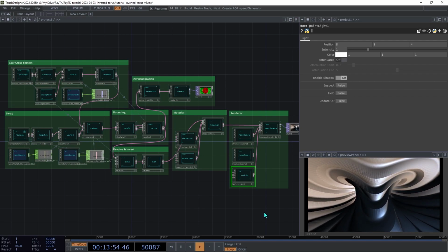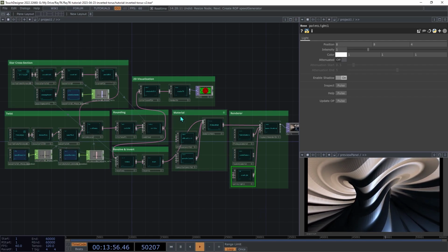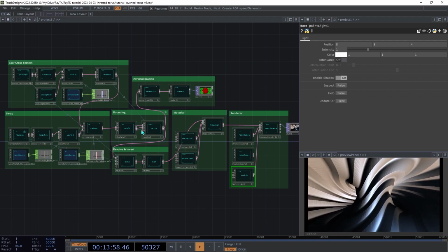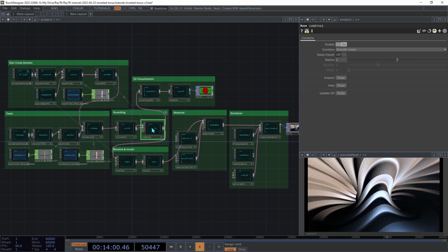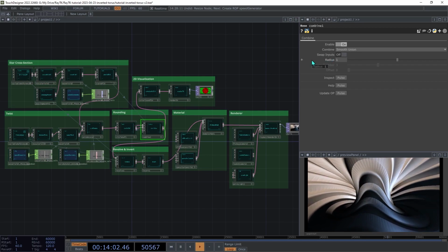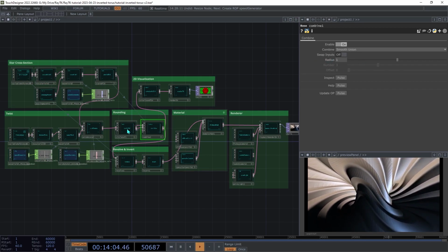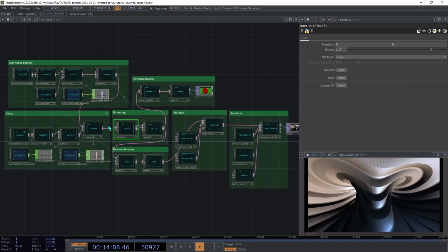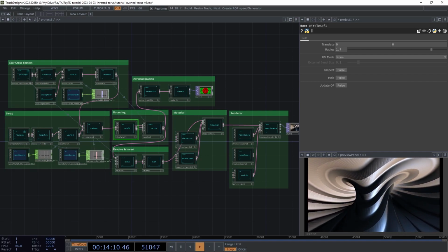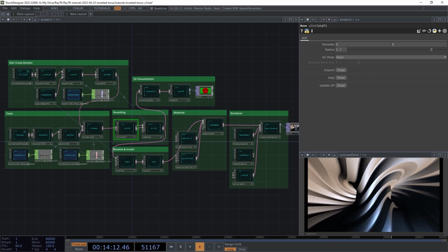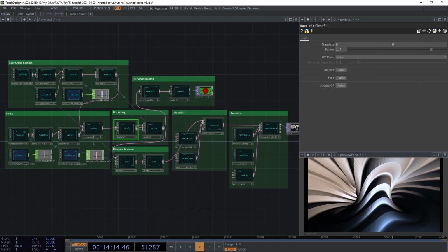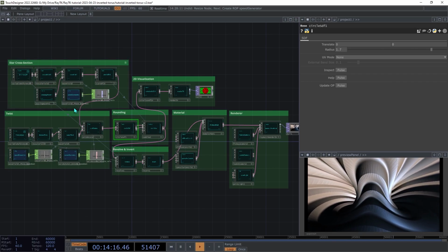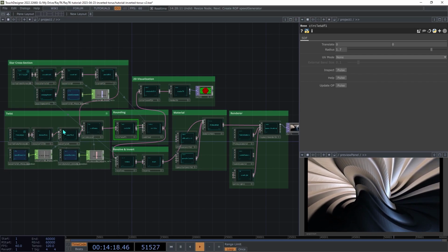If you want to expand on the scene, some potential areas would be to experiment with the balance between the circle and the star, using either the blend radius on the combine or the radius on the circle, or both. You could even use a field to control the blend radius, similar to what we're doing for the cross-section rotation here.